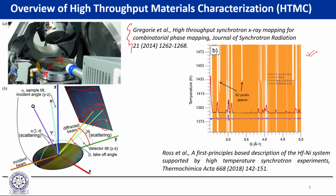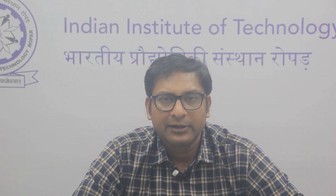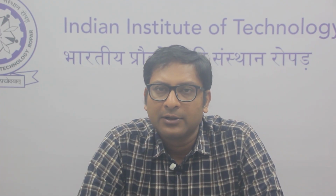Here what we have done is we have taken this hafnium-nickel 50-50 composition, and we have heated it to fairly high temperatures. As we are heating, we are collecting the X-ray diffraction data simultaneously, and as with the previous experiment, all of this data collection is being done in transmission mode. Therefore it's only a very short interval of time in which we are collecting the data, and that allows us to have fairly good resolution in terms of time as far as our data is concerned.